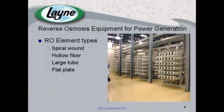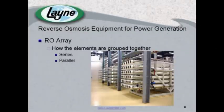Element. There are really four basic types of elements: spiral wound, hollow fiber, large tube, and flat plate. Each of these has its own advantages and disadvantages, and I encourage you at the end of this slidecast to go ahead and download the white paper where all of this is explained in much greater detail. An RO array is really just how the elements are grouped together. Typically you're going to see these in series or in parallel.